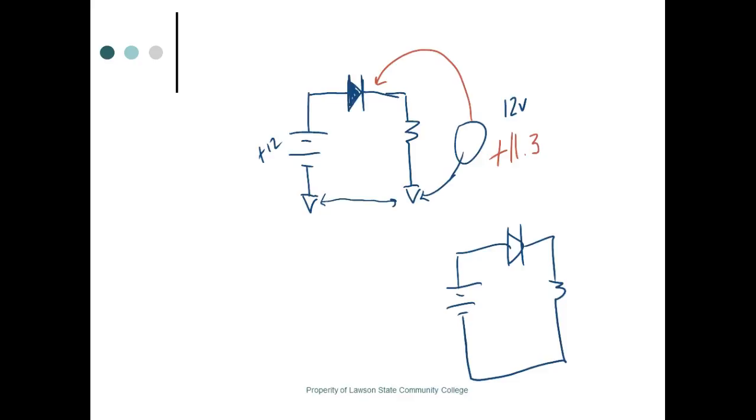It don't make any difference the size of this resistor. If that was a 1K and I had another 1K, that would drop, but the diode drops 0.7 of a volt. Supposedly, we know right now that it doesn't drop exactly 0.7 of a volt. It starts conducting around 0.5. Then it varies with current. But for me to know the exact voltage, I would have to know a lot of stuff about the diode. But look, by George, they're both positive.